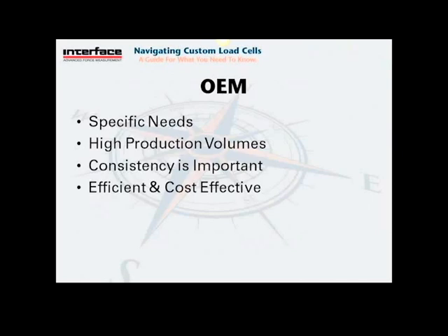For example, we had a customer come to us with a lumbar table, and they had already designed the table and had instrumentation. They wanted a solution that would basically plug into their system, give them the force readings, and basically plug and play. So what we did is we spoke with them about which type of load cell they needed, the size, capacity, and then we asked them what type of cable lengths they needed.